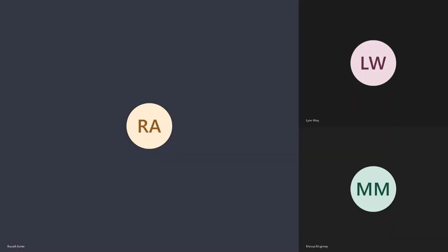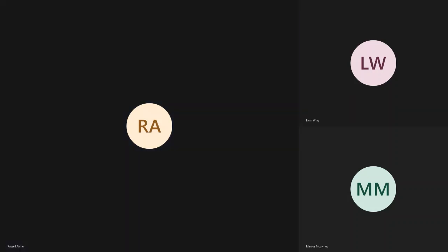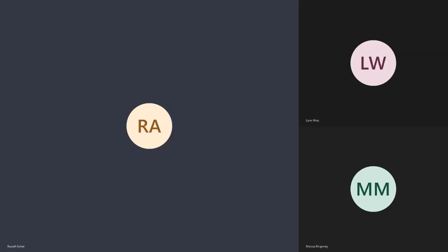High spatial complexity requires large storage resources, and reality usually has gradual boundaries. That's a big one. Contours. We're saying anywhere on that contour has that same elevation. Well, what goes on in between the contours? All we know is the elevation can't go above or below one of the 2 surrounding contours. We don't know what's happening in between.